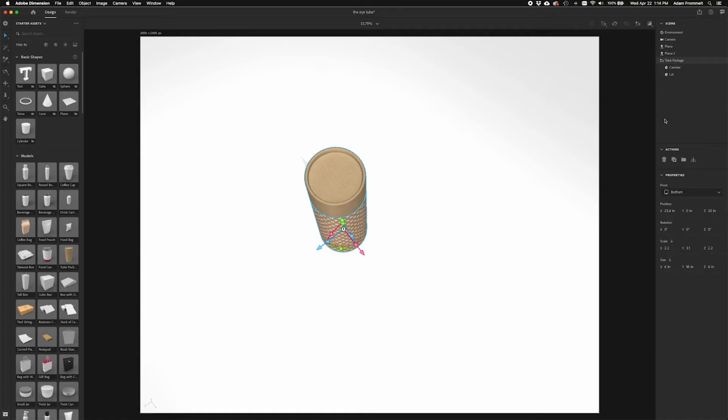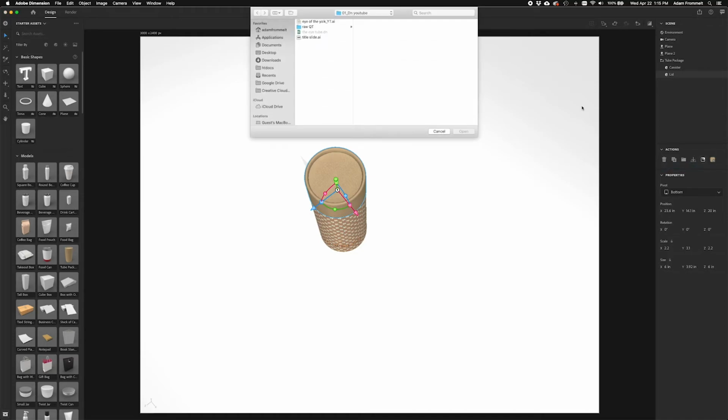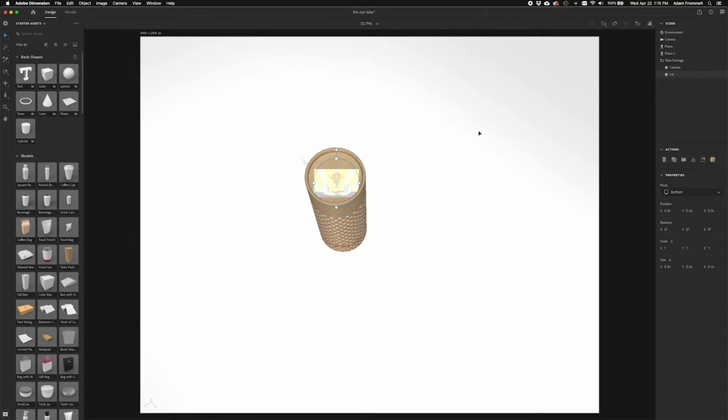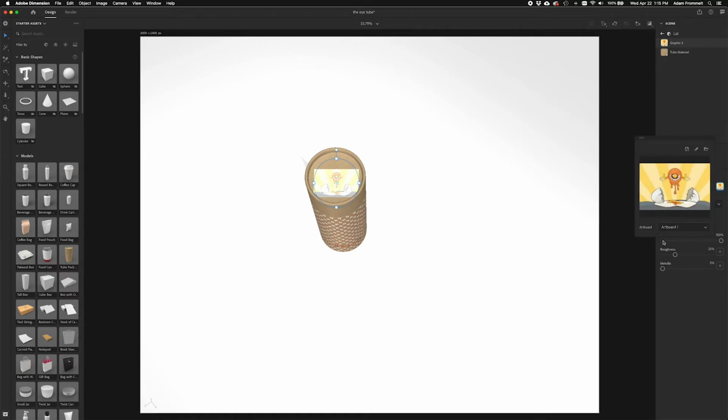And then the rest of the moves I'm going to do on the canister, I'm going to hit at the material stage. So I want to click on just the lid, and then back to my place graphic on model, my same file, and I want to be on decal for placement. I'm going to click on thumbnail, switch out my artboard.